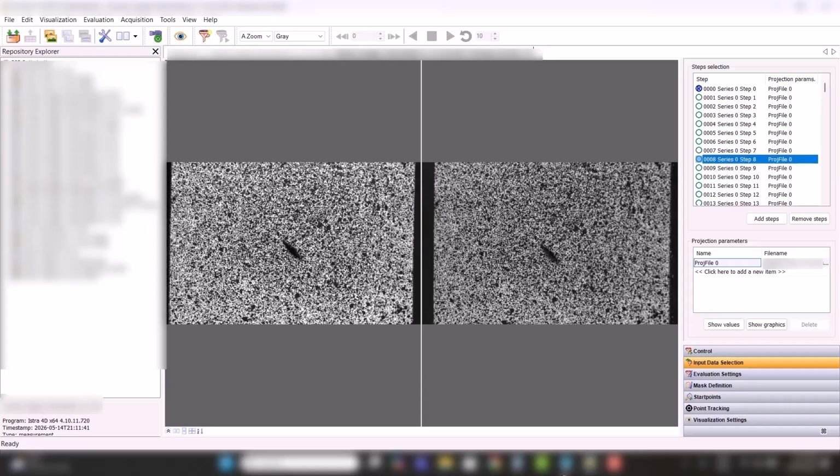Okay, so why not just add 100 rung steps? Well, for every rung step, there's going to be a little bit of precision loss, so you don't want to just arbitrarily add rung steps. However, if a rung step is added at a position where it's needed, then the accuracy lost because of the gap bridging is made up for, and most likely and then some, by the accuracy that would have been lost if the DIC algorithm didn't have that bridge to work with.